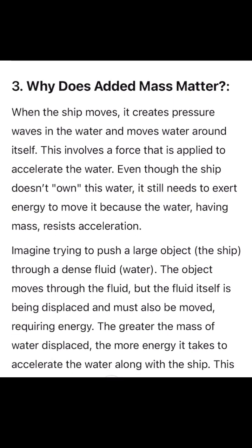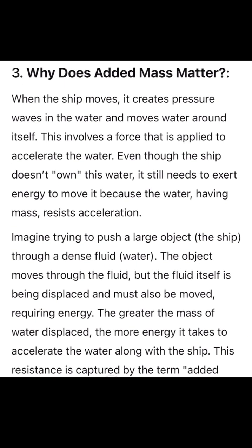When the ship moves, it creates pressure waves in the water and moves water around itself. This involves the force that is applied to accelerate the water. So we need to apply some force that will accelerate the water. Even though the ship doesn't own this water, even though it's outside the ship, it still needs to exert energy to move it, because the water, having mass, resists acceleration. Any object which has mass will resist acceleration.